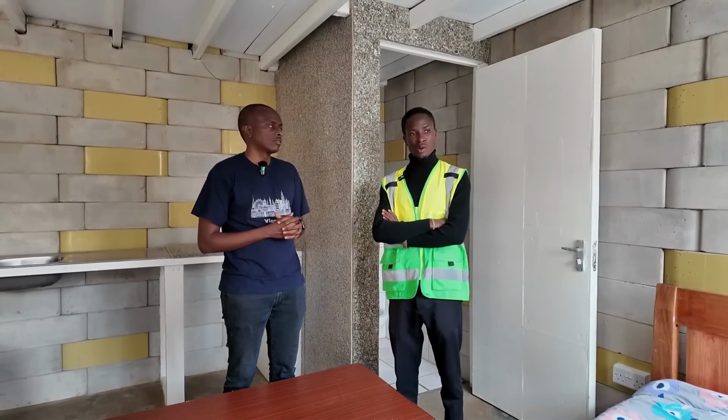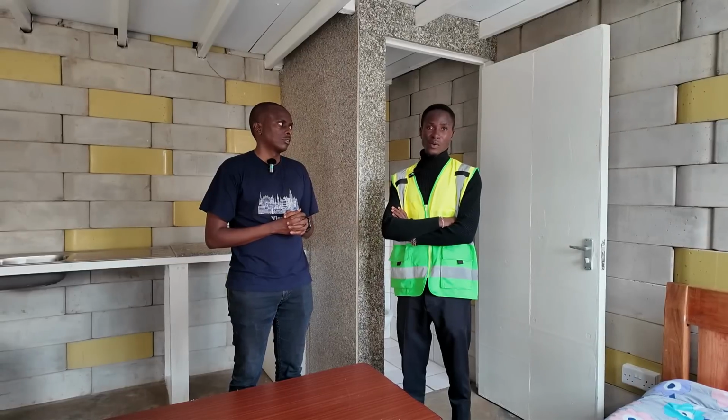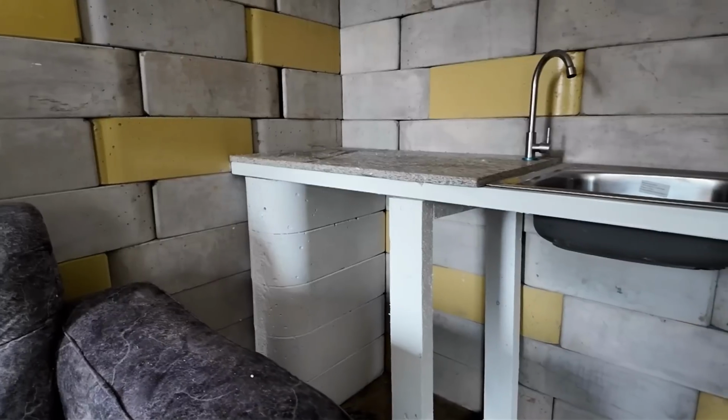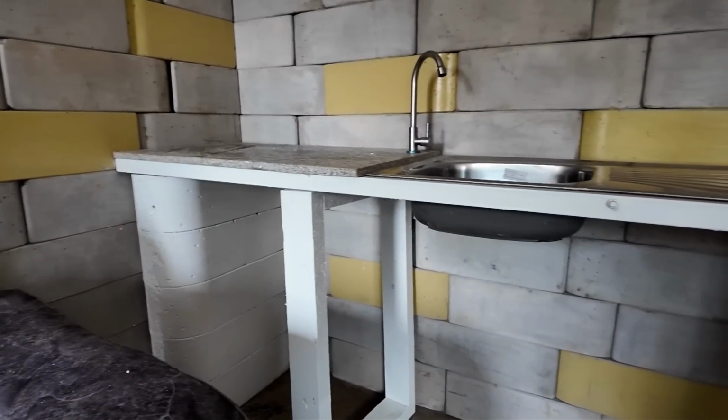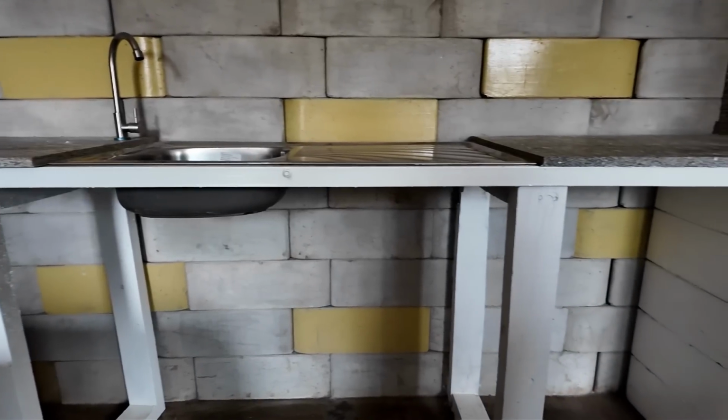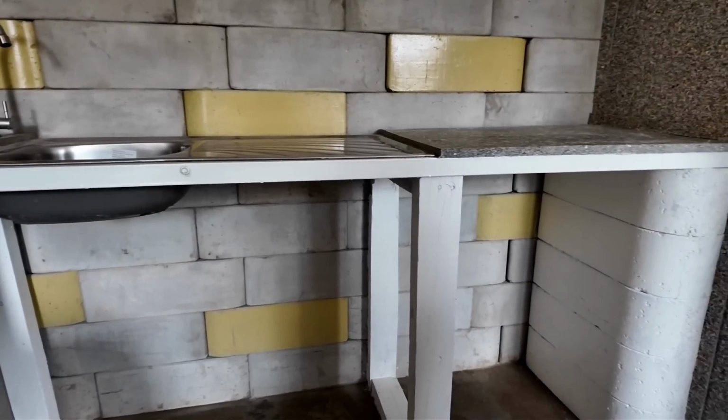So once you've bought the twist block, and if you're doing a ground floor structure, you just stack them appropriately, do some color schemes on the blocks, and then that is it. So you'll be able to save on the other materials. That is the mortar that you could have used for the joint work if you were to use a conventional building way, the plaster itself, the formwork for columns and beams, and the way we do our electrical works. The conduits pass through the blocks, the plumbing works pass through the blocks. So the client is able to save a lot in terms of material, time and the labor that is affiliated to the project.